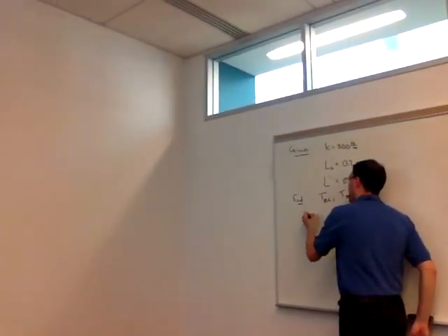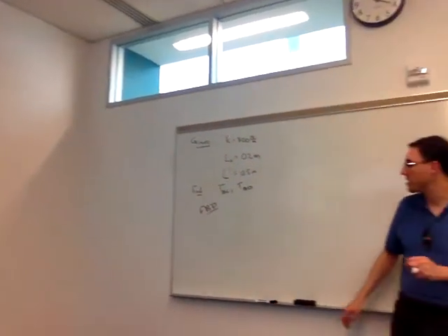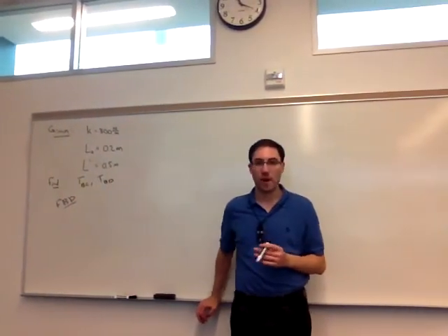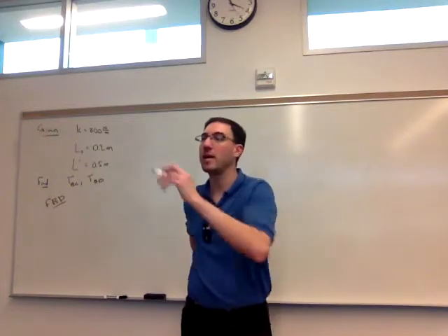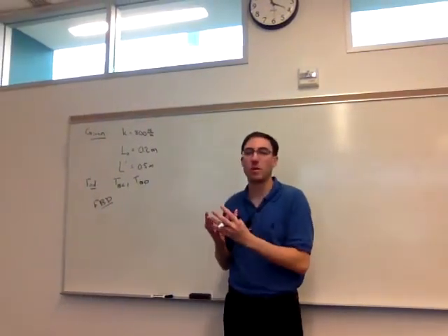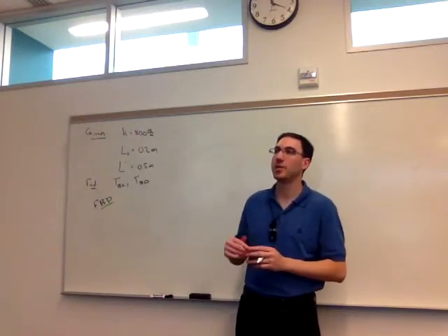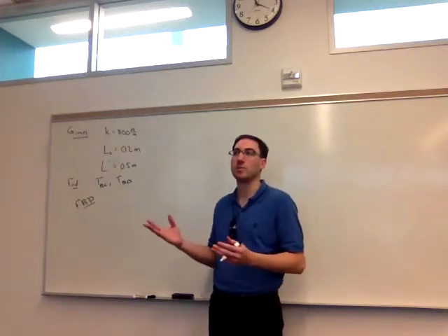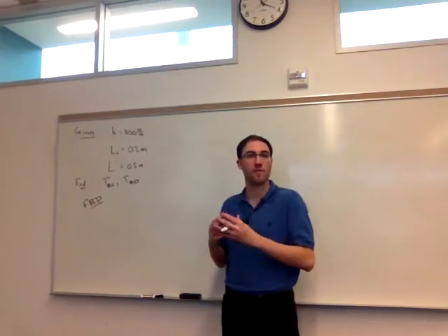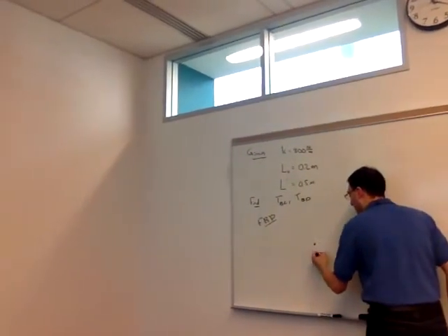Now we have our free body diagram. So first step of the free body diagram is we want to do what? Right, what's the point of interest we want in this problem? Right, so B, again, for particles, it's usually pretty apparent. But B will touch the tension in BC and BD. For example, we selected A. It doesn't touch BC or BD, so we're not going to be able to see the force in BC or BD. So B is our best choice here.